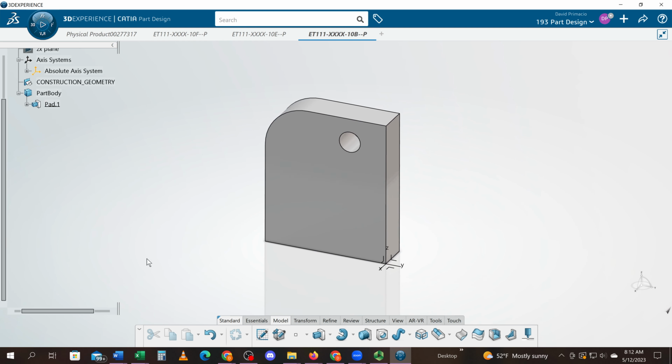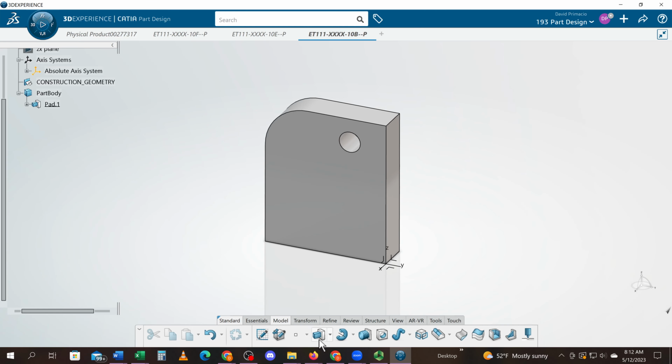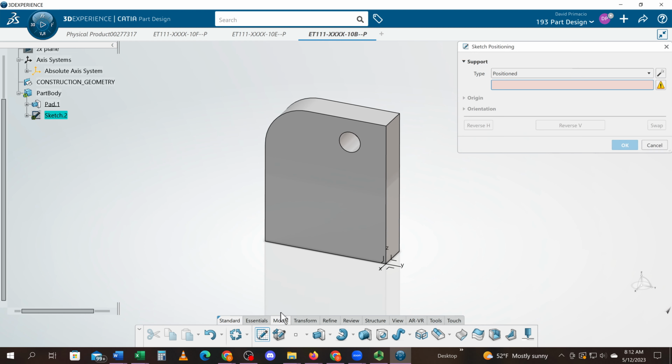Now, remember from the 12-step program I showed you how to do a position sketch. So what I would do next is create this pad right here that's 5/8 tall. So what we do is we go to position sketch. Select on this bottom line. And if it's not letting you get the edge, you have to turn this on so it knows you want to grab an edge.